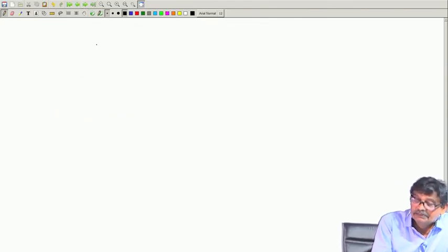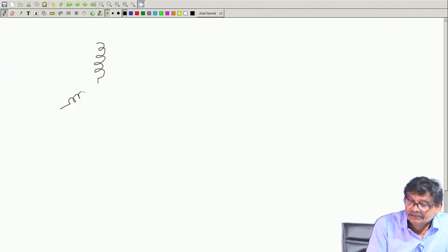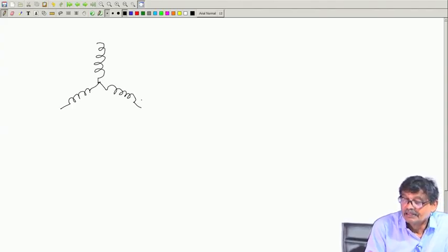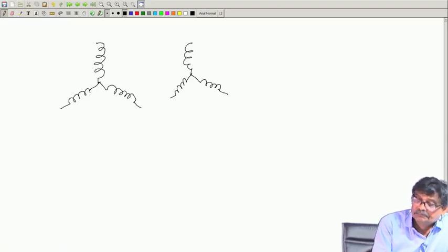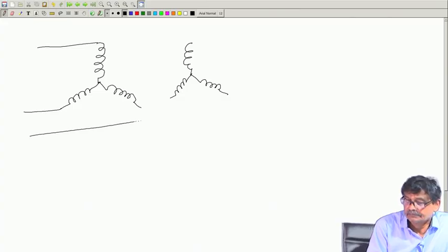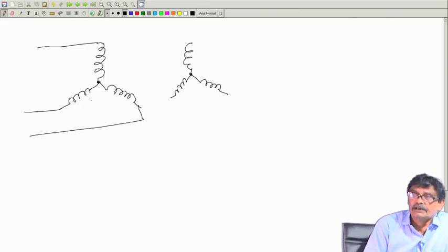Achha, another disadvantage of star-star connection, let me continue with that. Suppose you have a star-star transformer, primary and secondary both star-star. And of course neutrals are not connected anywhere, they are living their own life.